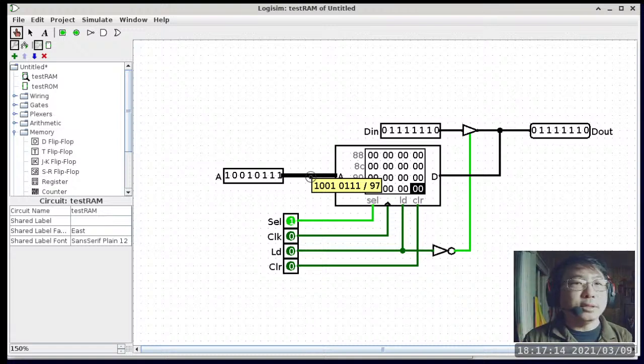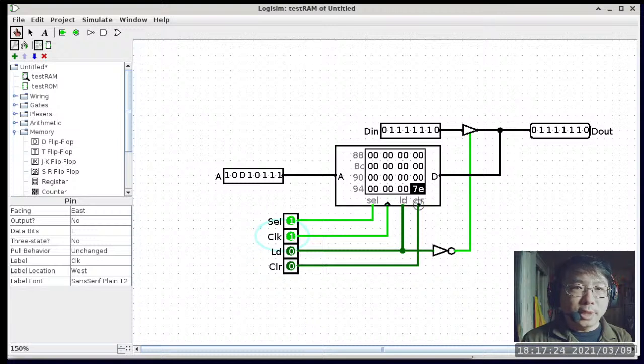So everything is now set up except for the rising edge. When I change the clock pin from a 0 to a 1, it updates the content at that location. So this is kind of cool, right? Next, we want to change the operation. This operation is done. This is called a write memory cycle. You go to RAM, and it is now done. When everything is done, it is always a good idea to turn it off. You turn off the RAM and turn off the clock.